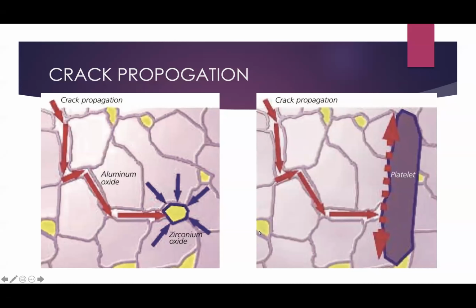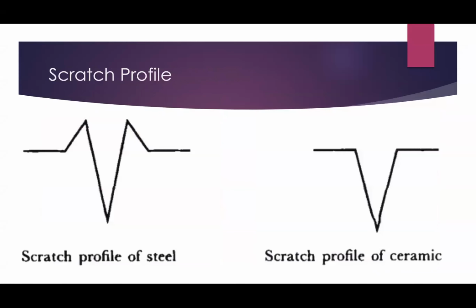The second one is in the form of these platelet-shaped crystals. So in the oxide mixture, you get these platelet-type crystals, as if you've had a bleed, and you're basically clotting off the crack. So that's the way to think about it, okay? Think of it in terms of conversion reinforcement and also platelet shaped crystals as well. Those are the 2 ways that you stop crack propagation.